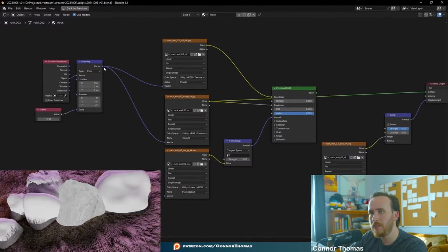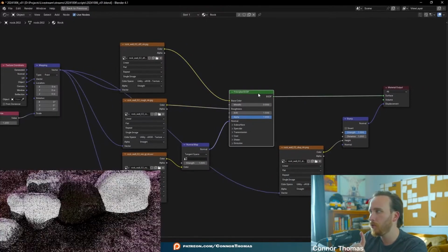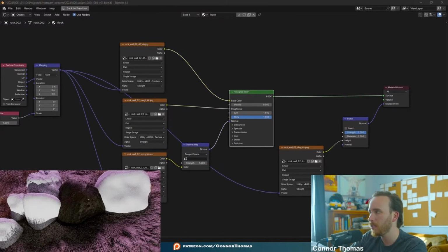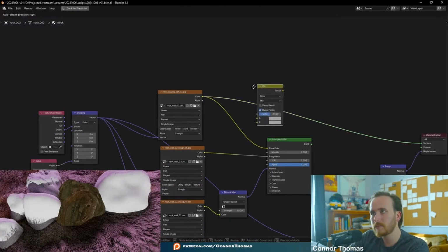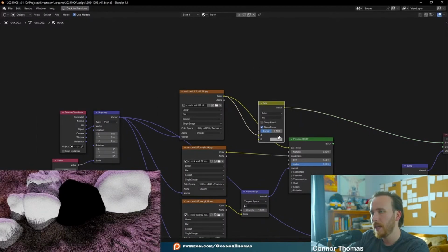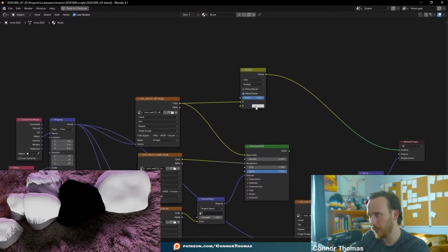Now, with that being said, we want to plug this vector into all of our different image textures that we have. Now, this is not procedural, so this value here is the only rock texture that we're ever going to get. So let's do this. We're going to do a mix color node, and we're going to just plug that in there. And then this value here, we're just going to have that pure white right now. And under our mix option, let's just change this to multiply. Okay. So now with the factor set to 1, we should have our diffuse texture here multiplying against a white value.